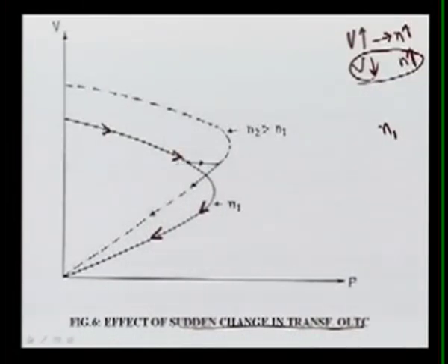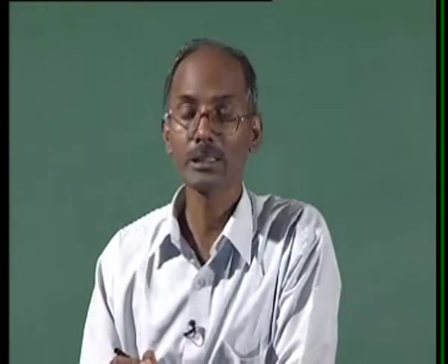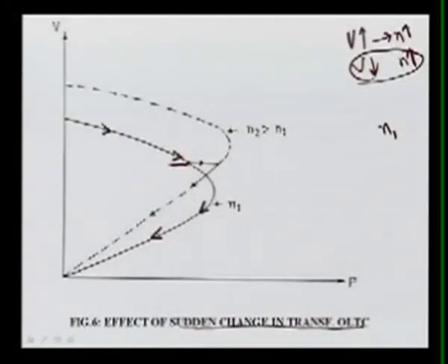If the voltage reduction goes beyond a certain value here, suddenly we are increasing the tapping, meaning we want to increase the voltage here. What happens here, the voltage will try to stay constant and it will come here, and you can see at this N2 tap our PV curve will be this.